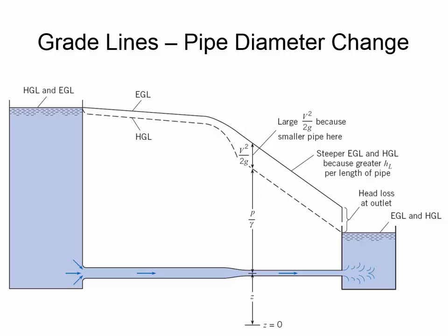the line. And one of the things I want to point out here is that the HGL intercepts the water surface, but the EGL is above the water surface, and then suddenly it goes down again. So here the velocity head is being lost. As the water goes in, see these little blue lines inside of the tank? These little blue lines are kind of just trying to give you the idea in your mind that all of the energy that exists as the velocity head is lost because the flow just diffuses. When the water goes into that tank, all of the energy that existed as velocity head is just poof, it's gone. And so this is the graphical representation that the EGL is above the water surface and now it's at the water surface itself.